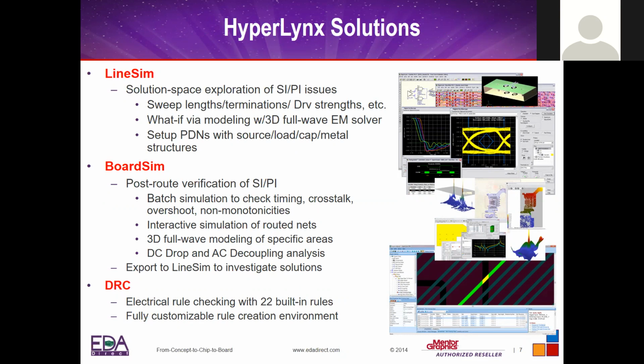Things like that. And also for DDR interfaces, it gives you the ability to test drive different technologies. Should I use a by 8 chip, by 16, by 32? Should I use Micron, or should I use Samsung, or whatever? So those are the benefits of doing pre-layout analysis.